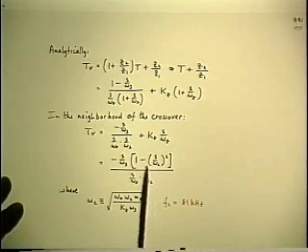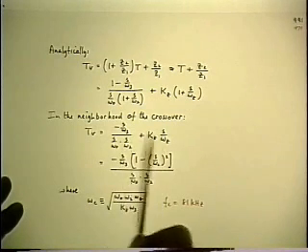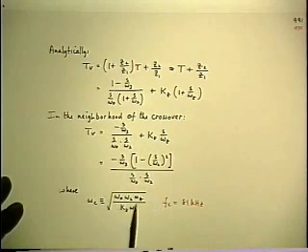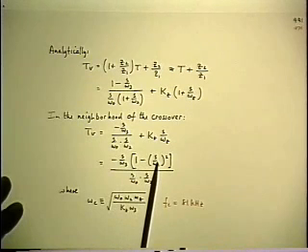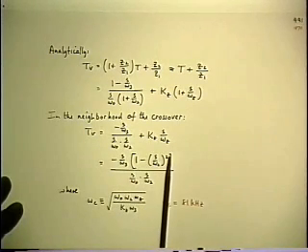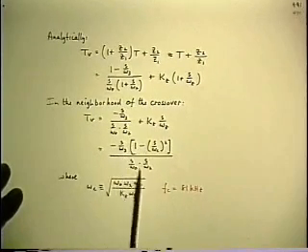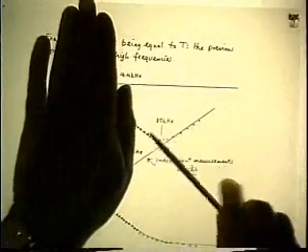And I know what that corner frequency omega c is, because I get it when I factor the S out. When I factor it out, omega c is equal to this stuff. So I know what it is analytically. The square bracket is now identified as a multiplier on the high frequency asymptote for T. In other words, that high frequency asymptote for T is this one.